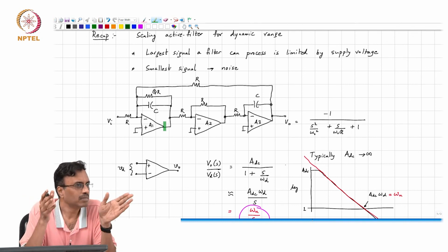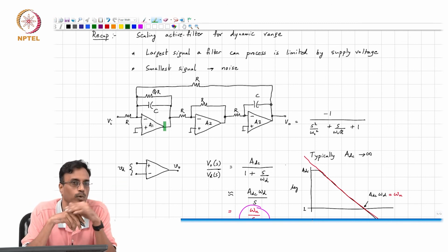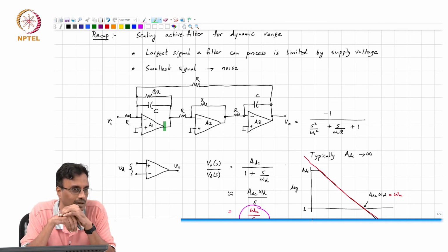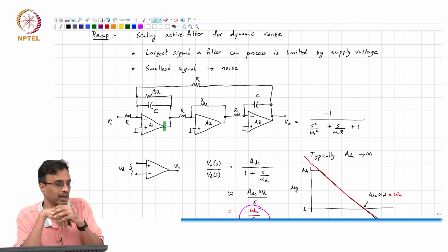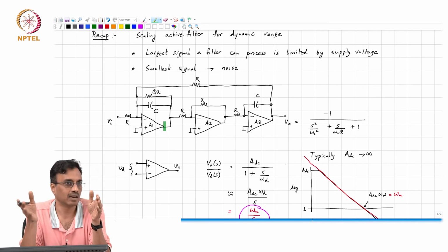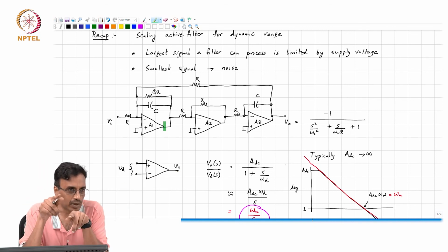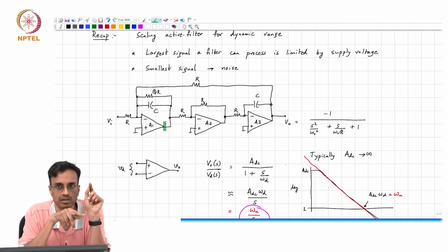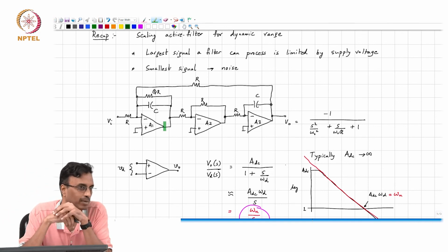It will tend to become unstable, or it will become closer to getting unstable, right. So, in the parlance of poles and quality factor and so on, what should we expect before doing the math? If our op amps are non-ideal and have some delay associated with them, the integrators also have delay associated with them. They are now embedded inside this negative feedback loop. Earlier, without delay, the quality factor of the poles was something. And what is the interpretation of the quality factor? It is how close those poles are to the edge of instability, right.